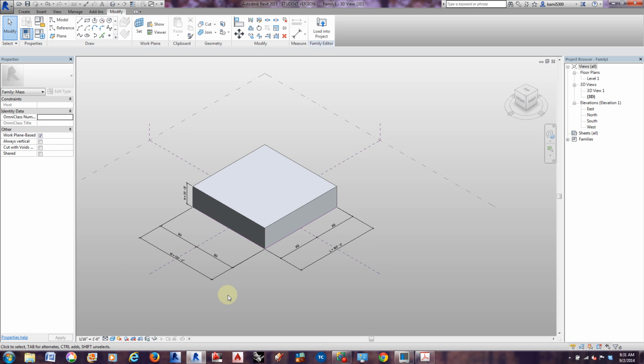Okay, so now this line is equidistant to this line, so it's a square. Now we want to make one dimension from this line to this line and drag it out here. And how do you change the little height of this with the cube? So cancel out of that, and select this just like we selected this guy, and add a new parameter called edge.